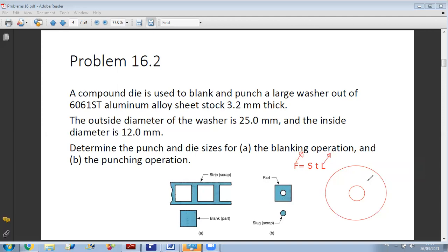Okay. If you perform just the blanking operation first and then punching operation, or punching then blanking, so the press size will be imposed by which operation? The blanking or punching? You are using the same press, okay? So one press will have one maximum capacity. So since this press should have a minimum capacity to perform this operation, who will impose the minimum force of the press? The blanking operation or the punching operation? If you are doing them separately,